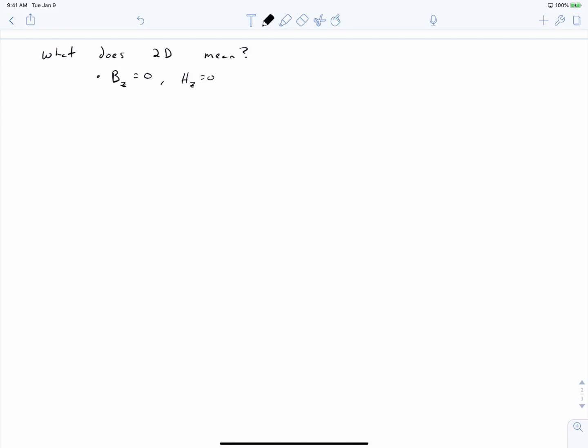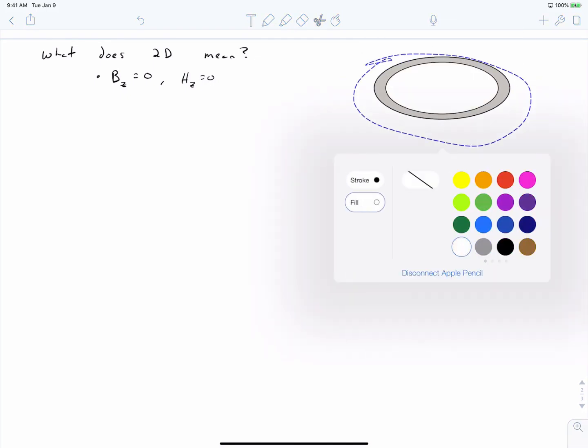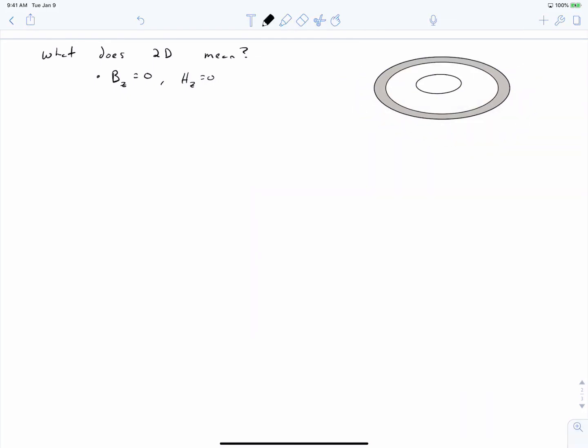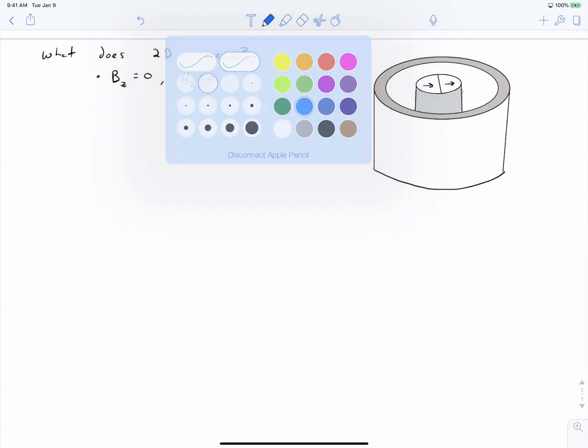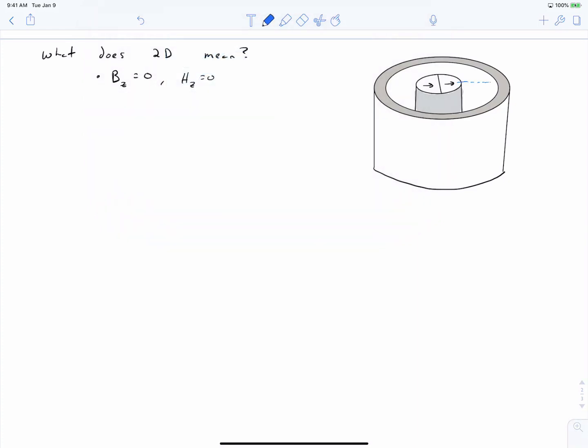It basically means that if we were to take this example motor here, this is a trivially simple example, and so what I'm drawing on here is a permanent magnet rotor inside of a stator. And I'm trying to draw this in 3D, if you excuse my drawing skills. So we've got this permanent magnet rotor inside of a stator, and our field is going to do something like this. It's going to come out of the rotor, and it's going to go into the stator, and then return through the ferrous steel back to the rotor.